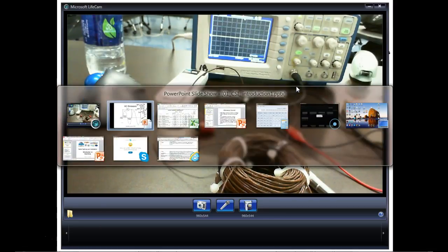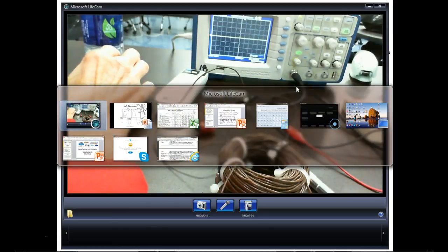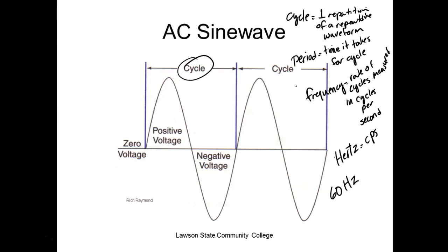So why do we want to step the voltage up? Well, Alabama Power is not delivering current, they're not delivering voltage, they're delivering power. So we have this magic formula where power is equal to V times I. What happens when I'm at my house and I turn on a 100-watt light bulb is my power company has to give me 100 watts. But they don't have to give it to me at the voltage at my house. So this is the magic formula right here: I is equal to P over V.